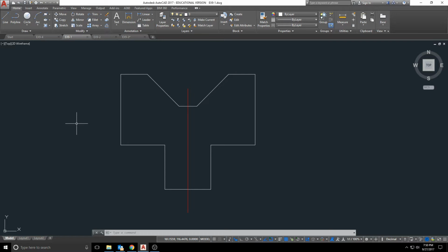So when the QA inspector goes in and checks dimension number 1, as long as it is between 37.95 and 38.05 millimeters, then that part is considered to be within specification. So with that in mind, we need to begin to implement these onto the CAD drawings.